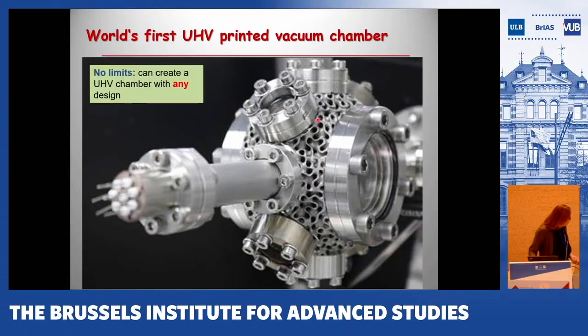So what is 3D printed is this body that you can see here, and you can see this funny foam-like structure, and the reason for that is that you can remove material and still get optimum stability. Even if you know that your system will suffer from some kind of stress because you, for example, send it to outer space, then you can create some reinforcements in the places needed.